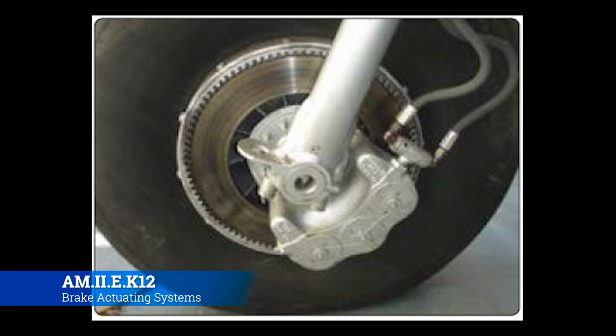All right, so the 8083 says the caliper straddles the disc. It has 3 cylinders bored through the housing, but on other brakes, this number will vary. I'll tell you that most of your Cessna 182s, your Piper Cherokees and stuff, they only have one caliper. They won't have the full 3. Usually the 3 you'll end up getting in the bigger, more complex aircraft.